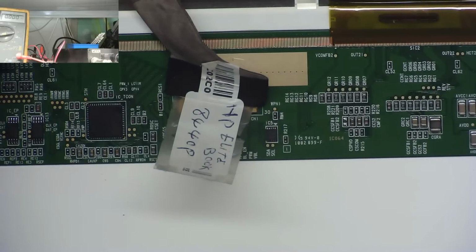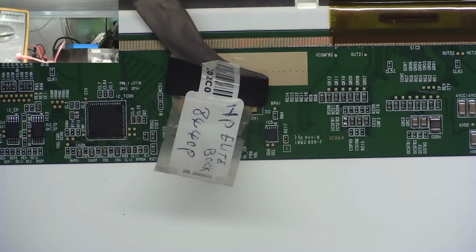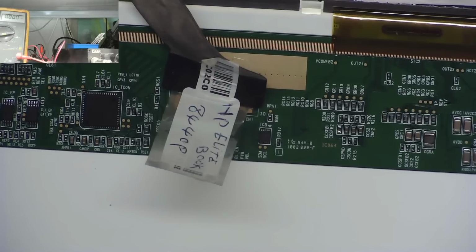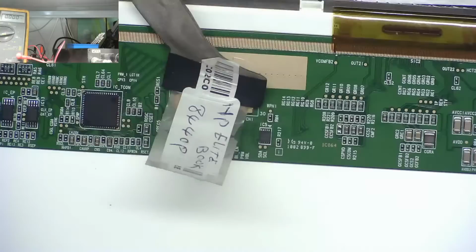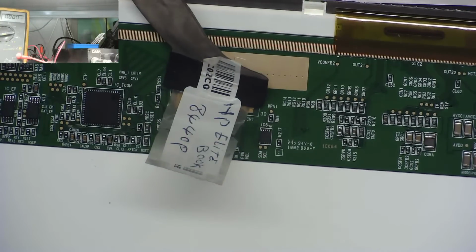See if any data, they're not. Normally I expect them to be a bit warm. I think we're going to have to look up the data sheet of some of the chips on here and see what we actually have. And then once we've done that, maybe we'll find some points we can test with the oscilloscope to see why we appear to have all the voltages present but no signal, no data on this one.